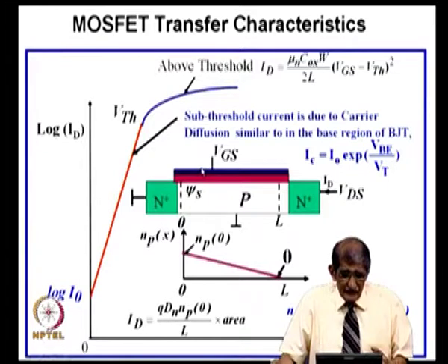See, when I apply voltage plus here and ground here, between the gate and this point there is that VGS. You can see that at inversion, watch this carefully, when you applied plus voltage, the electron concentration was equal to the hole concentration at this end.